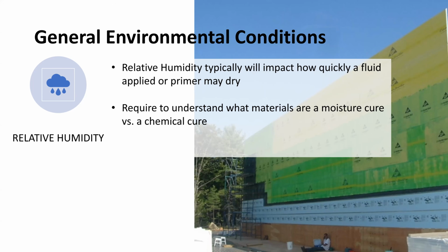If it's more of a chemical cure or a solvent-based material, then it's not necessarily impacted by relative humidity as much. But if the relative humidity is really high, these things can take quite a bit of time to actually cure up, right? With some of these, specifically things that are sprayed on like a spray foam or a fluid applied. So you do have to be careful, and even the relative humidity can impact how these things cure.